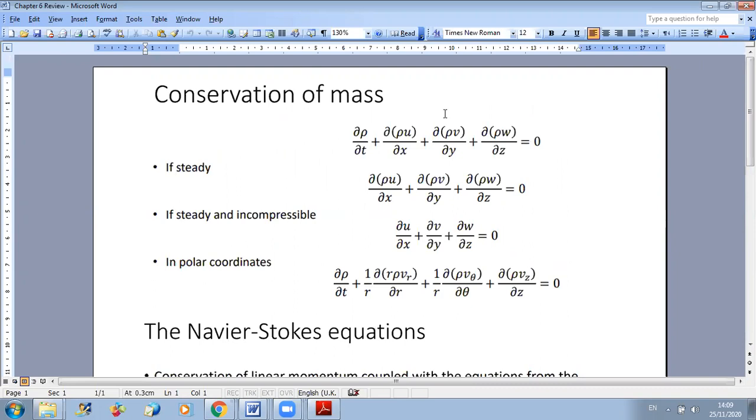First, here we are not in polar coordinates, we are in Cartesian coordinates. So please always write them in the problem. Even if you know the solution or it's straightforward, write the equation and simplify it to get your result. Here it's a 3D flow, steady and incompressible, so I will use this relation. Now I will start to simplify it. Always look at the inputs of your problem, and depending on them you should know which terms will be simplified.